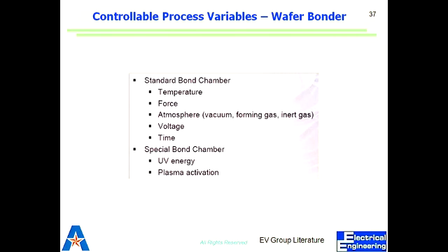So in the case of a wafer bonder, we have temperature, force. We may be providing a gas, or we may not, apply voltage and do it for enough time. We get the wafers bonded together. What we have can give us nanoscale precision. So you can make devices on both of them, and ultimately bond them together. We have the capability of aligning at nanoscale. That's a new machine we have.